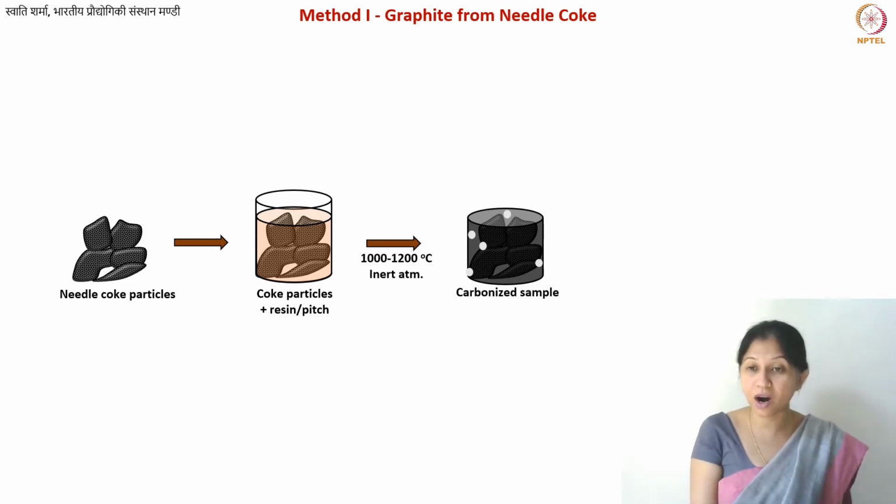So that can lead to hardening. We'll also learn about some polymers that can be cross-linked by exposure to UV light. These are known as photoresists, and this is what we use in photolithography. So there can be many ways of cross-linking the resin, but the idea is to harden it.